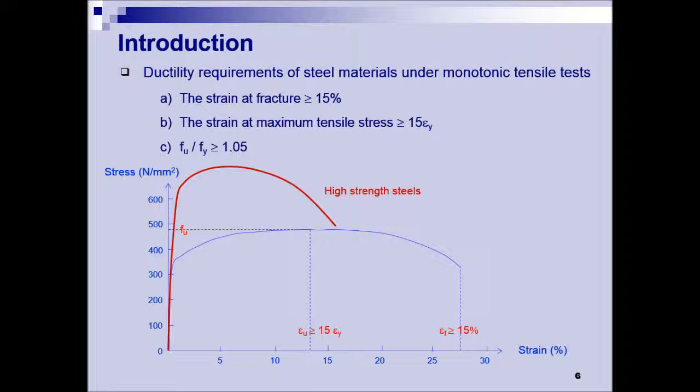However, a lack of information can be found in the literature supporting these quantities. In reality, steel materials should be designed to resist cyclic loading due to seismic actions. The seismic requirements for materials should refer to their hysteretic behavior rather than merely their ductility.